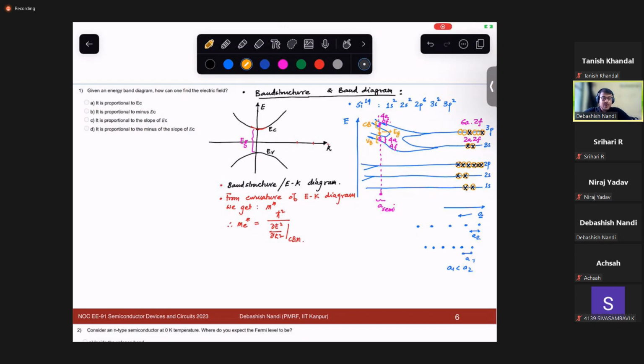The interatomic distance of semiconductors is such that it falls in the region where the band starts to split, because the neighborhoods of two atoms are very close. So the band splits and creates two bands, conduction band and valence band.